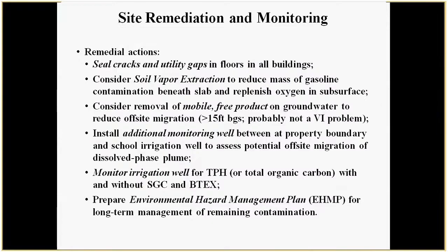Site remediation monitoring, the remedial actions here: they seal the cracks and utility gaps in the floors of all the buildings, even the one with a small pocket of gasoline-contaminated soil under the floor that could pose short-term vapor problems. Consider soil vapor extraction to reduce the mass of gasoline beneath the slab and replenish oxygen. Consider removal of free product on the groundwater. Again, once you clean up under the tanks and such, the free product on groundwater is mainly a problem for continued groundwater contamination, probably not vapor intrusion. It's just too deep. I'd still check.